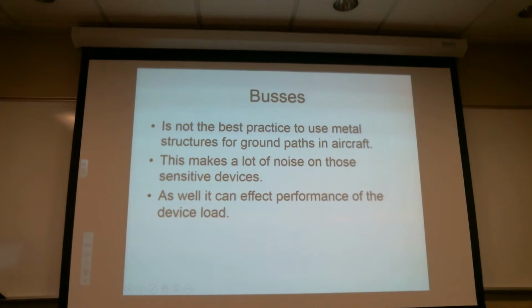But in an airplane, man, you're up there collecting all kinds of static electricity. The ability to have your nav equipment and your communication equipment work is pretty important, particularly in really bad weather. And running electricity through the chassis of the airframe can sort of interfere with that in some cases. So what I have found, particularly in audio circuits, is I've had to completely isolate the audio circuit from any ground plane. But in doing that, I then got the noise to go away.